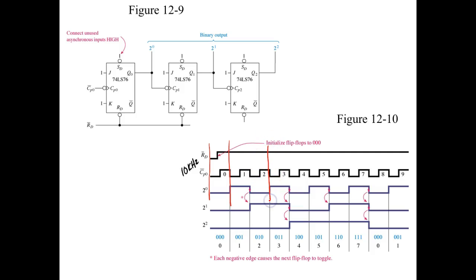Okay, so here I have 2, down here I have what? 1, right? You understand? Now look, this one will start from here. No, I'm sorry, we'll start from this rising edge here, to this rising edge here. So 1, 2, 3, 4. So every 4 cycles up here, I get 1 cycle down here. So this gives me a divide by 2. This gives me a what? A divide by 4. And the next one is going to give me a divide by 8.